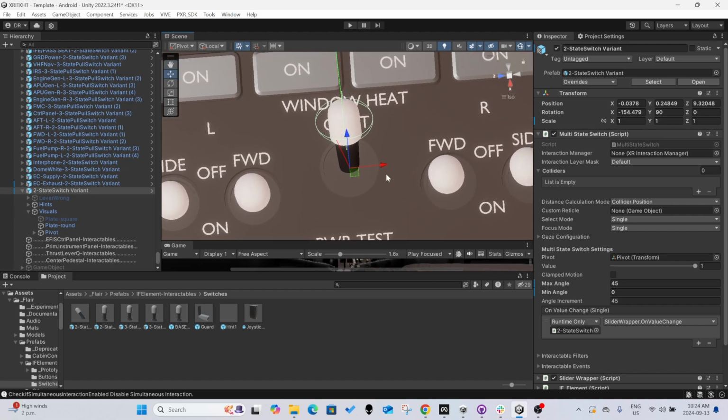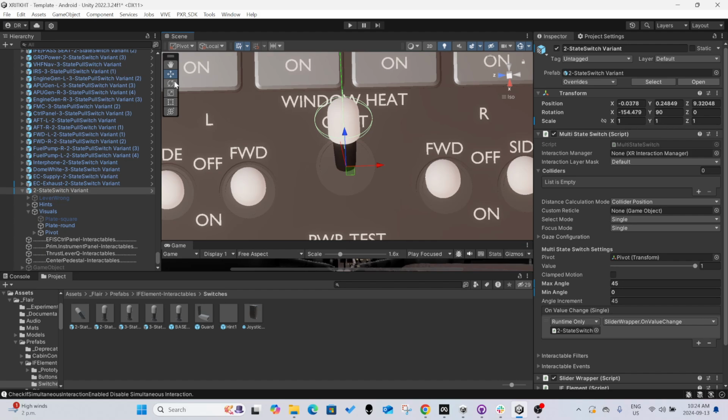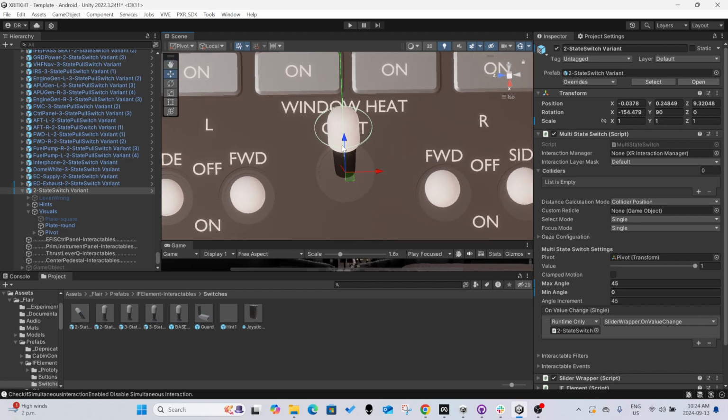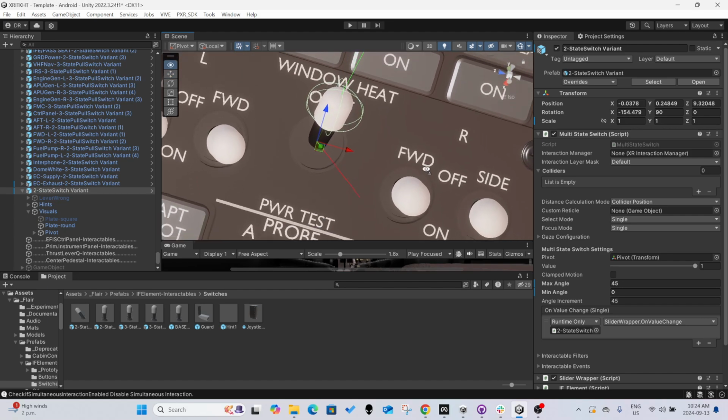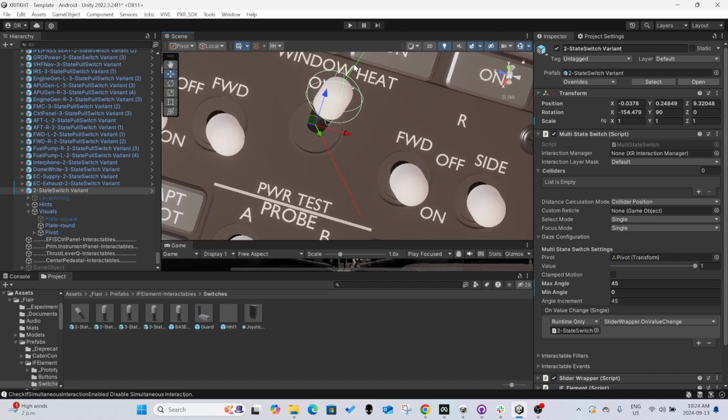Yeah, so that's how I want it, but I need to then rotate. So now you can see, since I want the green to match on, which is the position that it's rotated. So now green is rotated, and the other state is 0. So minimal angle is 0, maximum angle is 45. The steps, it's fine because I only wanted to move. It's only two states, so it can only have an increment of 45 from 0 plus 45. It adds up to 45.